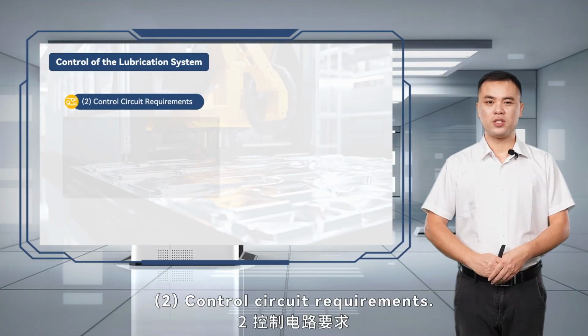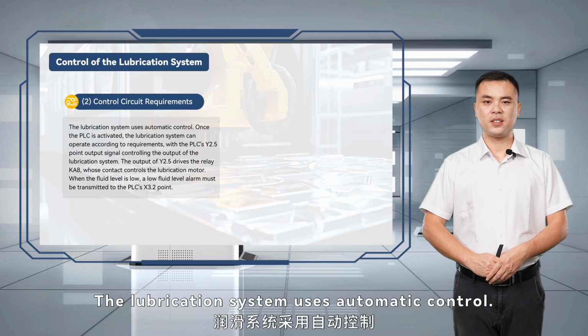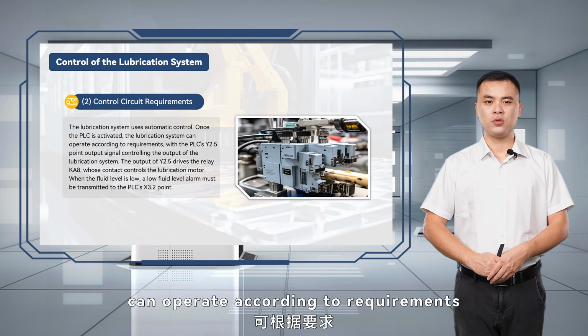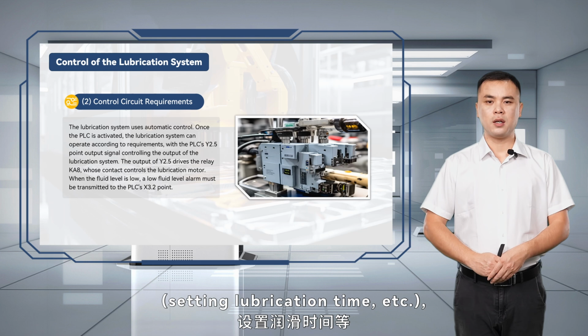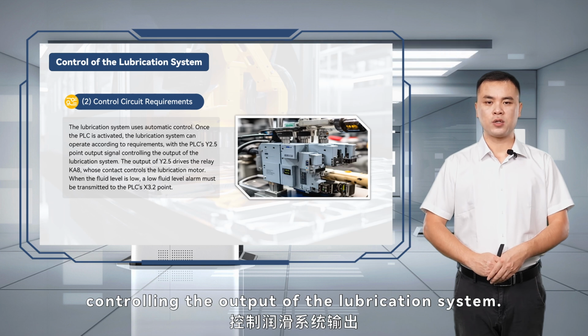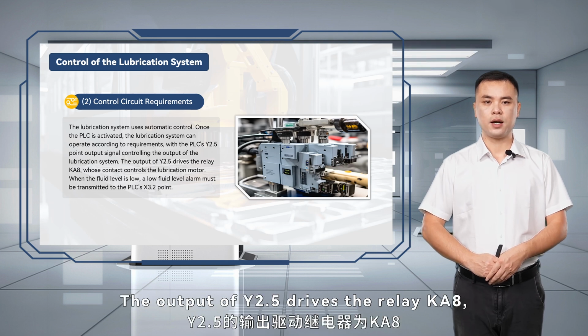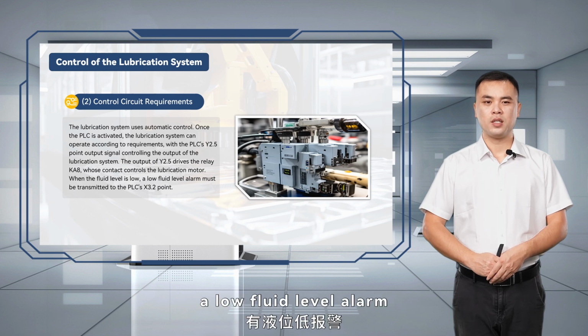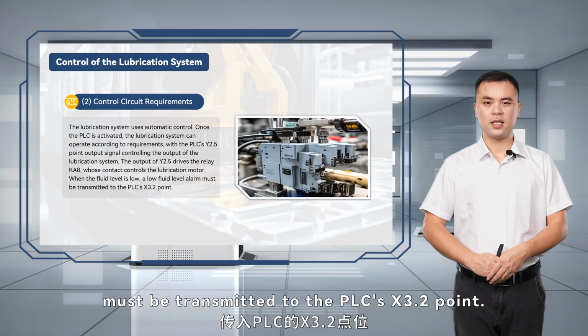2. Control circuit requirements. The lubrication system uses automatic control. Once the PLC is activated, the lubrication system can operate according to requirements, setting lubrication time, etc., with the PLC's Y2.5 point output signal controlling the output of the lubrication system. The output of Y2.5 drives the relay KA8, whose contact controls the lubrication motor. When the fluid level is low, a low fluid level alarm must be transmitted to the PLC's X3.2 point.